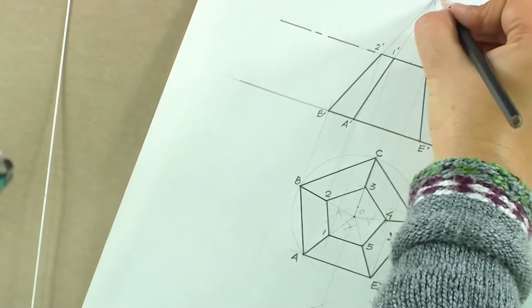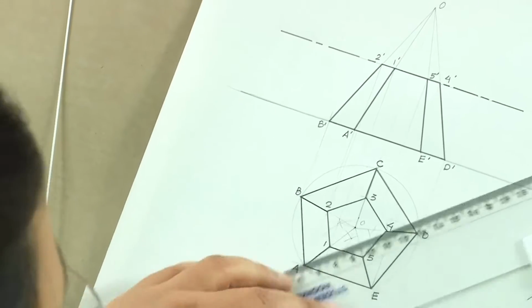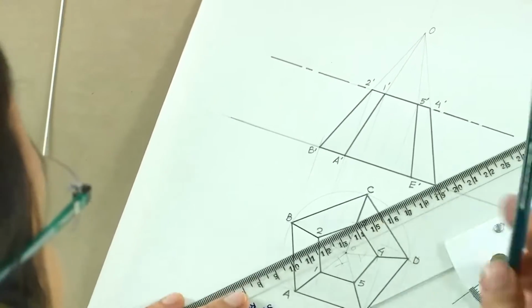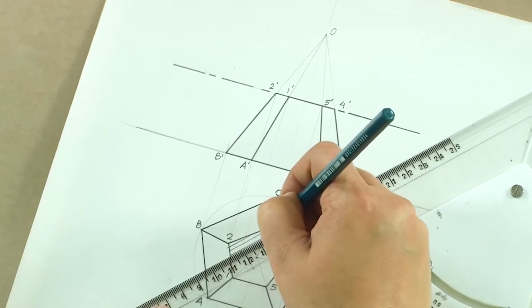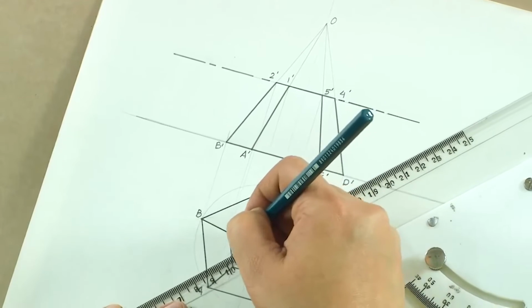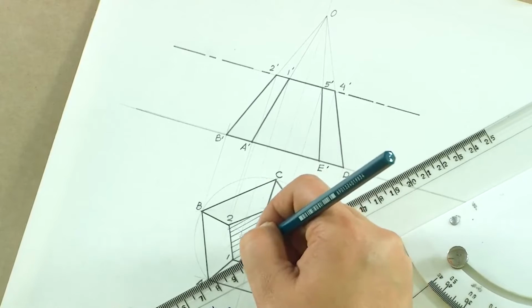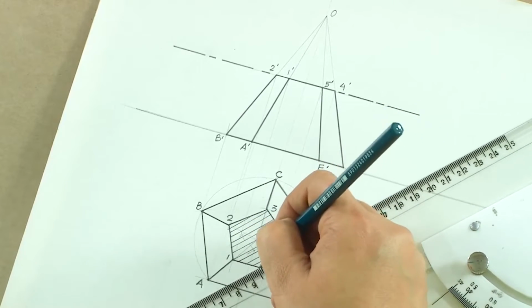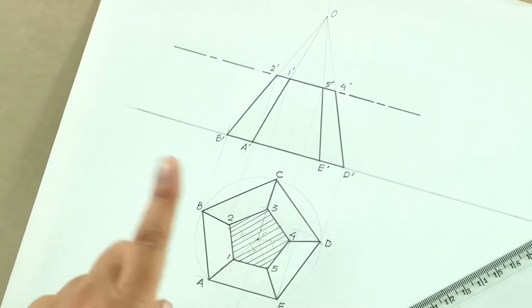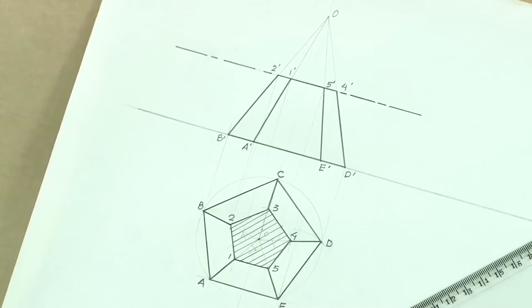So, this was the original O, which we have not darkened, and this is where the hatch is going to come. This is the section which will be seen. So, this is what we are seeing when the section plane is parallel to the base or perpendicular to the axis, and this is the true shape of the section. So, this is the first case when we draw the section of pyramids.